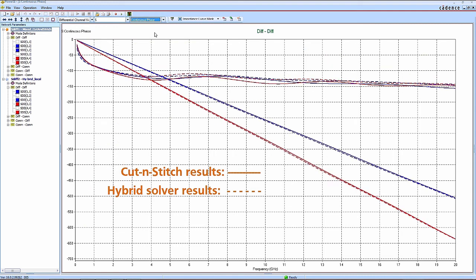The phase of the S parameters are also very similar between the 2 results. This implies the hybrid solver was overestimating the capacitive parasitics at the board side. Though this overestimation is only about 10%, it's the dominant effect in the channel, so it's good that we applied 3D simulation for it.